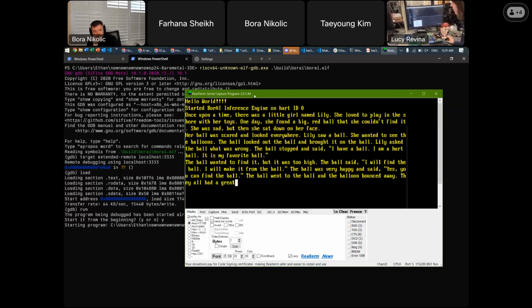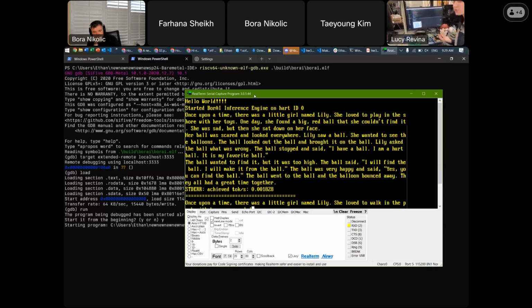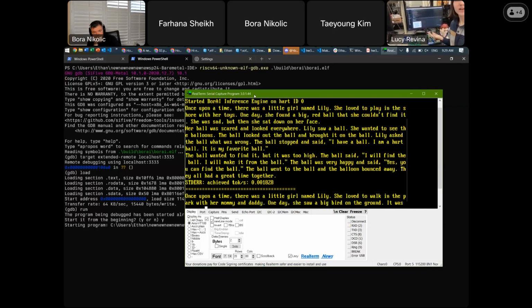So you see here it goes up to around 59 milliwatts. And we're very curious in seeing how these power spikes might be correlated to attention iteration. So how with every iteration of running attention, we might be getting power spikes. Again, a pretty short demo because we can run it with one click, which is really great because we've been able to automate a lot of the kind of laborious data collection across voltage, frequency corners, and use this in research and publications, as Bora mentioned, which is really exciting, especially for a class chip.